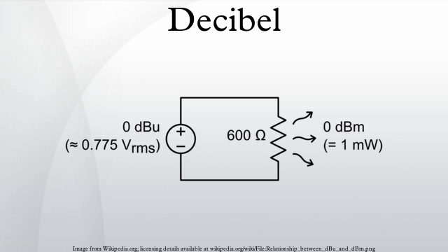The logarithmic nature of the decibel means that a very large range of ratios can be represented by a convenient number, in a similar manner to scientific notation. This allows one to clearly visualize huge changes of some quantity. See Bode plot and semi-log plot. For example, 120 decibels SPL may be clearer than a trillion times more intense than the threshold of hearing, or easier to interpret than 20 pascals of sound pressure.